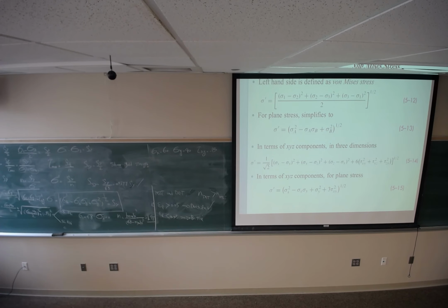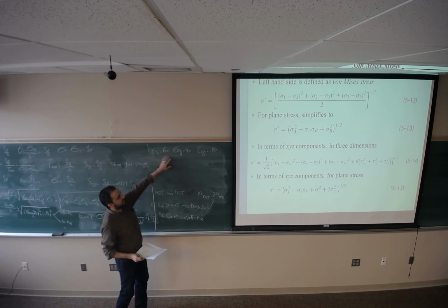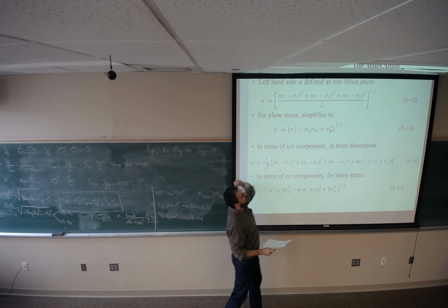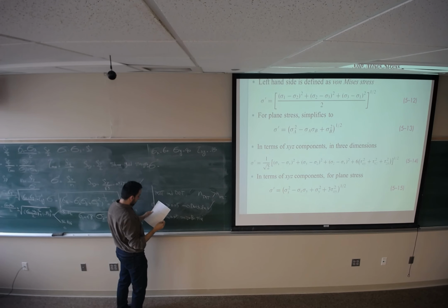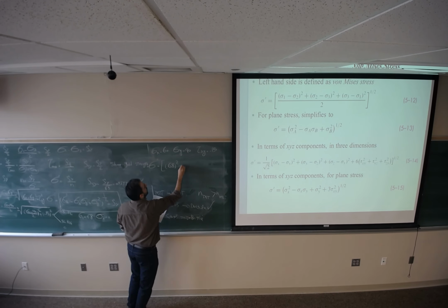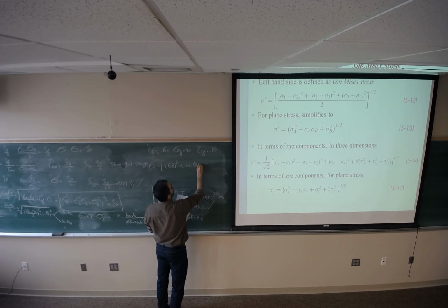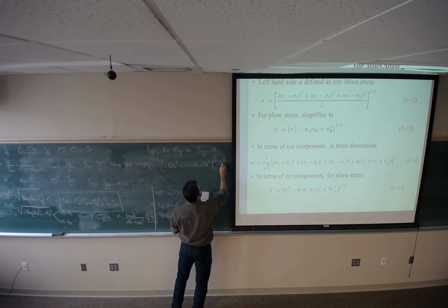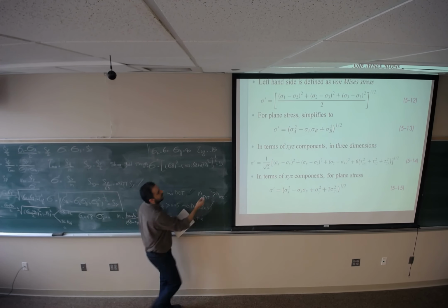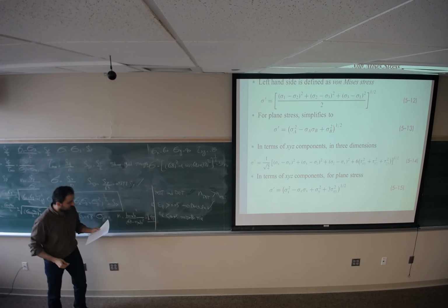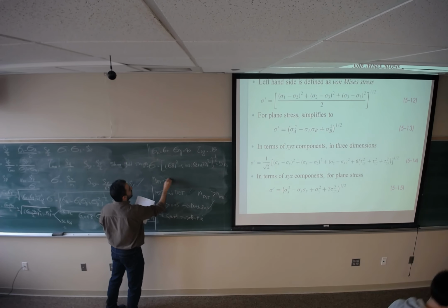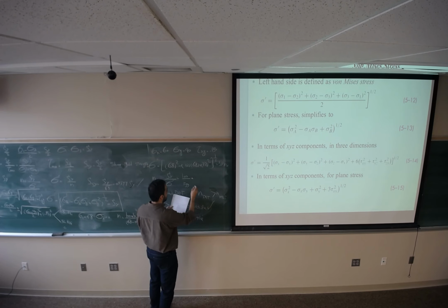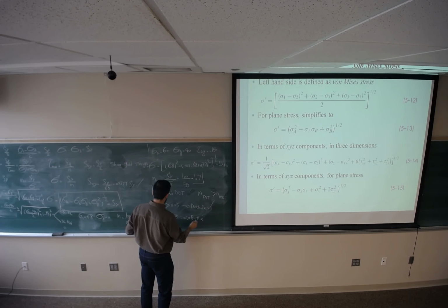I'm just saying, to save calculation, you don't need to calculate sigma A and sigma B if it's not needed. But since I already needed sigma A and sigma B for MSST, I'm going to use that. So sigma prime is the square root of 68 squared minus 32 times 68 plus 32 squared, which is 59. The unit is kpsi, whatever the unit of stress is. So n for distortion energy theory would be Sy divided by sigma prime, which is 100 divided by 59, 1.6, versus 1.47.